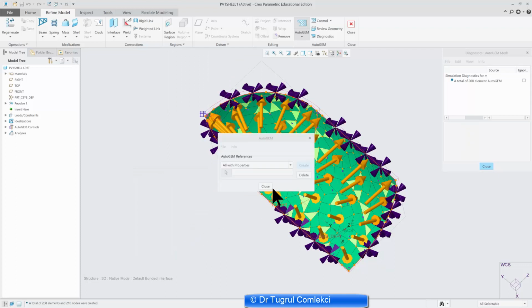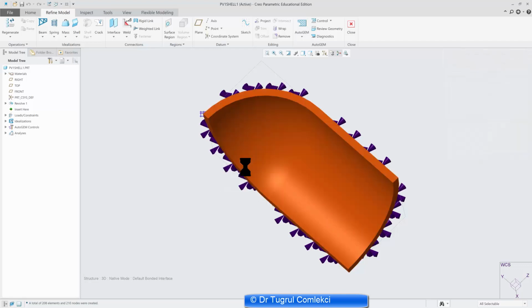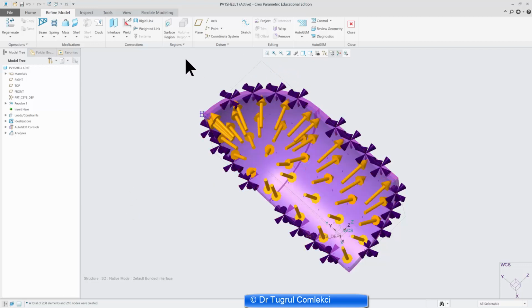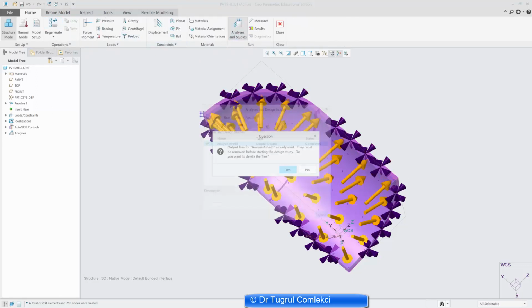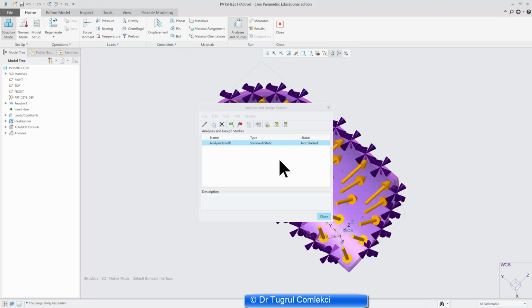and even this is probably far too much refined for these high order elements. So we can close that, and yes, to save the mesh. We can rerun this model, but we can also go to define our optimization. Let's do a first run to make sure that the higher order elements, denser elements, work fine as well. So this is running.